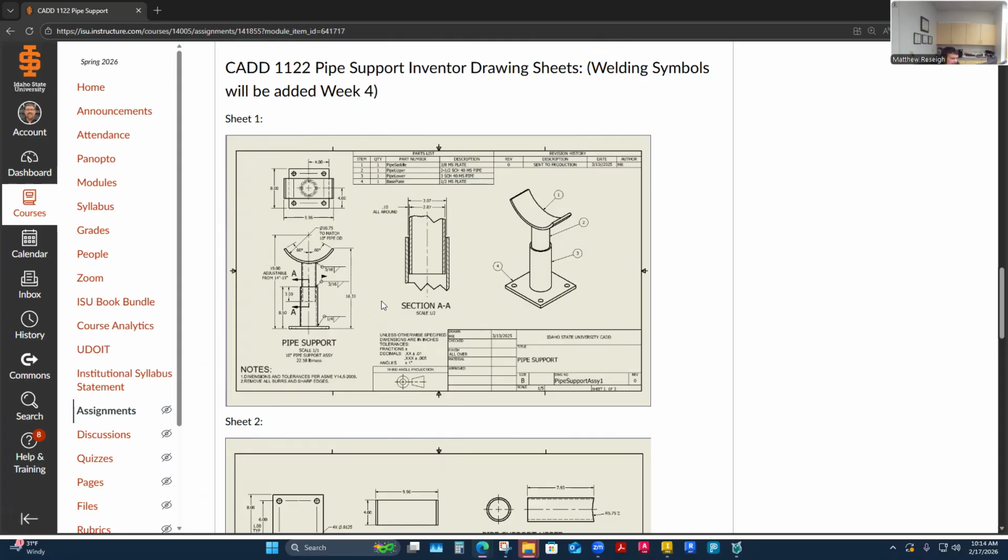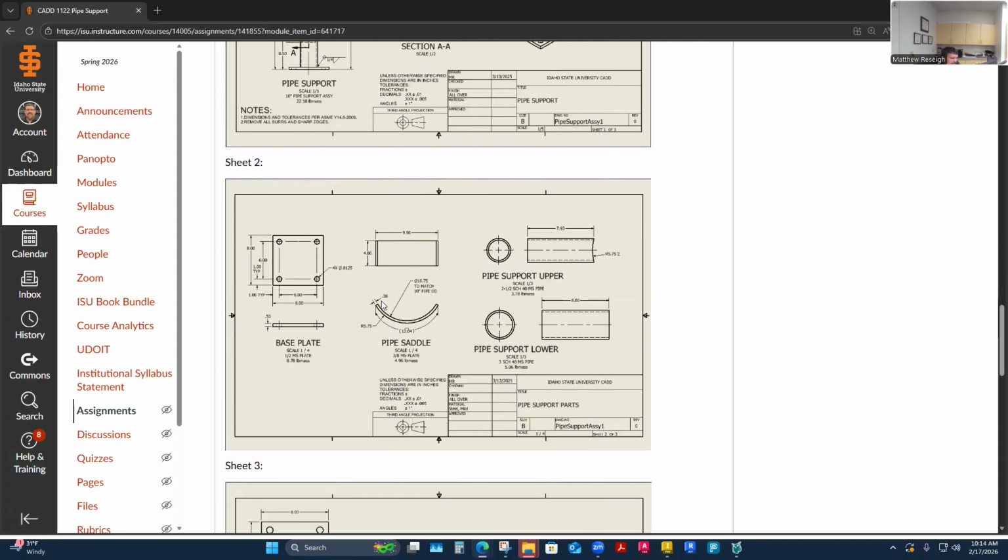Then I come down here and this is where I'm breaking out each part individually. I have a few different dimensions I can pull. This is called an arc length dimension. It's kind of the flat pattern dimension, but it's a reference dimension because I'm saying it's probably not accurate, just a rough. We need about 12 inches of material to make this. Looks like I'm using 2 decimal places on everything. I'm calling out what this is coped to of a radius.